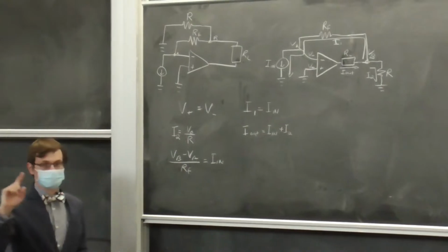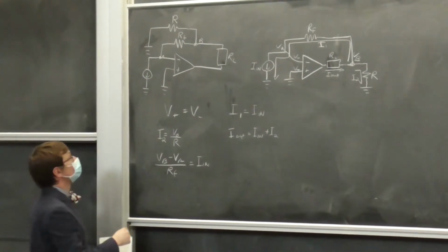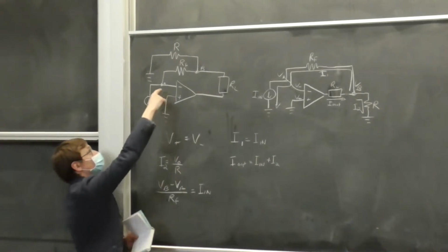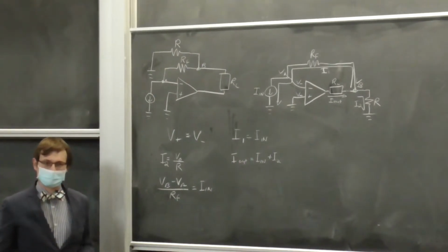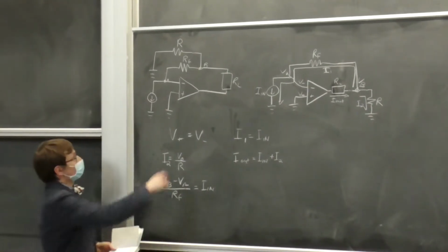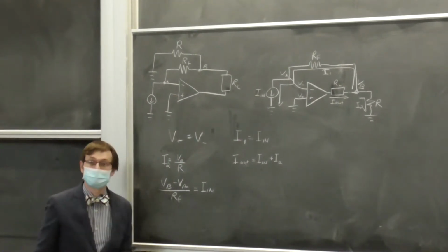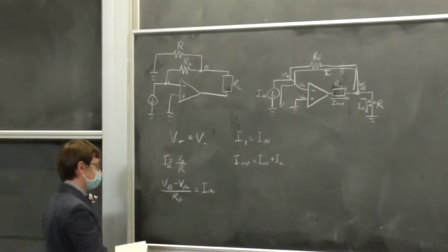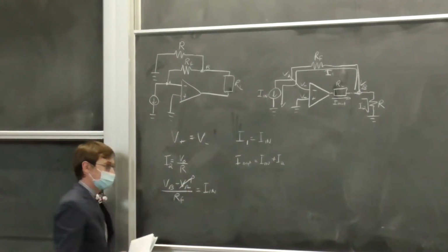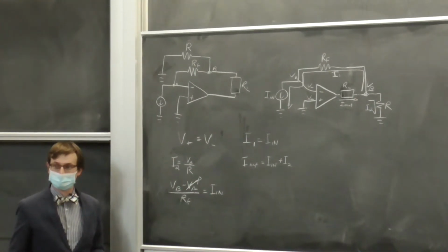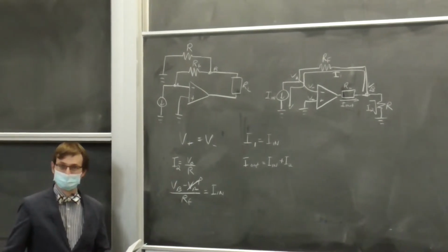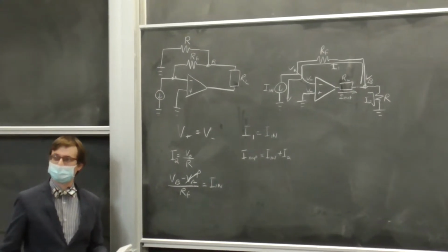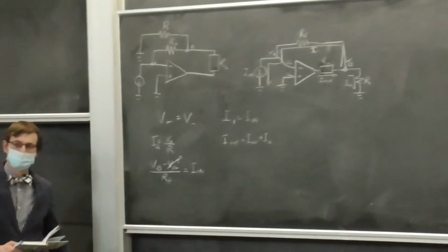Okay, so a couple of other observations, however. VA is equal to V negative, right? V negative is equal to V positive, and V positive is connected directly to ground. So we can actually write out that term entirely, right? Because of the OpAmp laws. Yeah? Any questions? Good.